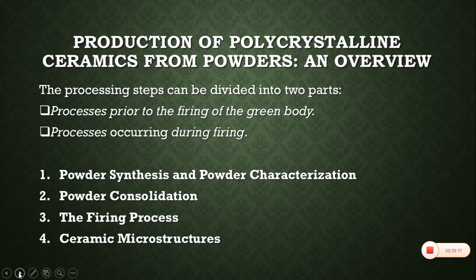For the powder synthesis and powder characterization, it is very important to select materials that are free from contamination, because contamination can alter the microstructure and will affect the properties of the fabricated material. So extreme care should be taken during the selection of the powder.